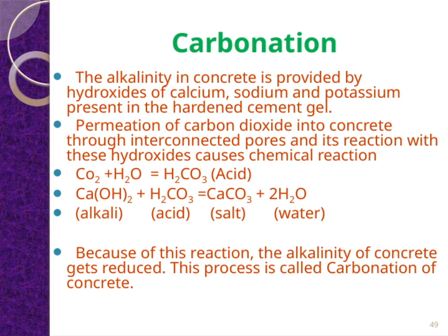It's a natural process, but it can have significant implications for the durability of concrete structures, especially in terms of steel reinforcement corrosion. So, understanding carbonation helps us assess the longevity of concrete and plan for maintenance or protective measures accordingly.